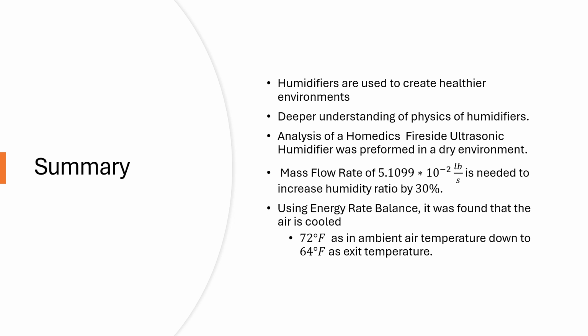So, in summary, we learned that humidifiers are used to create healthier environments, especially with allergies, which is useful in Tucson in the springtime. We now have a deeper understanding of the physics of humidifiers. From the analysis we performed in a dry environment, a mass flow rate of 5.1099 times 10 to the negative 2 is needed to increase the humidity ratio by 30% coming out of the humidifier. Finally, using the energy rate balance, we found that it cooled the air down to 64 degrees from an inlet temperature of 72.